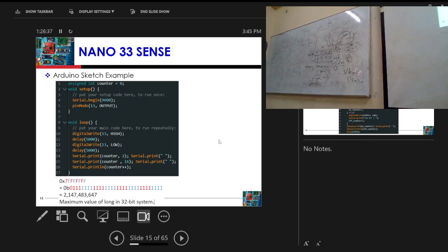Move forward. What do you mean by that? So for this, pay attention here. For this code, we are controlling a digital pin, which is pin 13. As I said, a very important thing: if I write the pin with just the number, it means digital pin. If I write it with an A, it's an analog pin. So here we are controlling the digital pin, and we are giving it a value, either voltage high or low. That's all. So it's a digital pin.